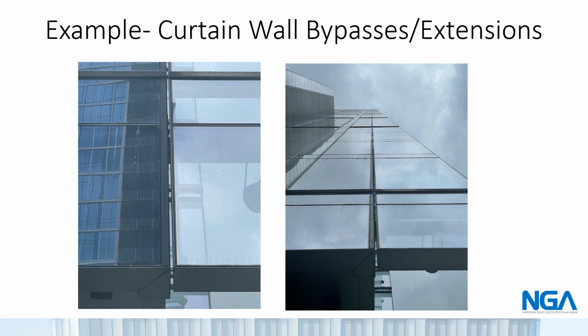The answer is yes. The building was designed to minimize thermal bridging. If you look closely, they did separate it. There is an extension. They were careful to separate it from the rest of the building. They reduced what would have been a long linear thermal bridge into smaller point thermal bridges.